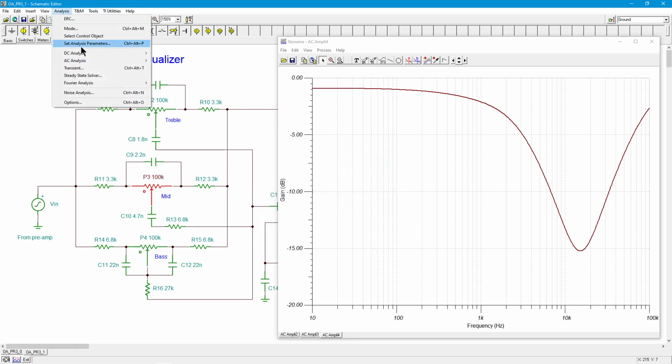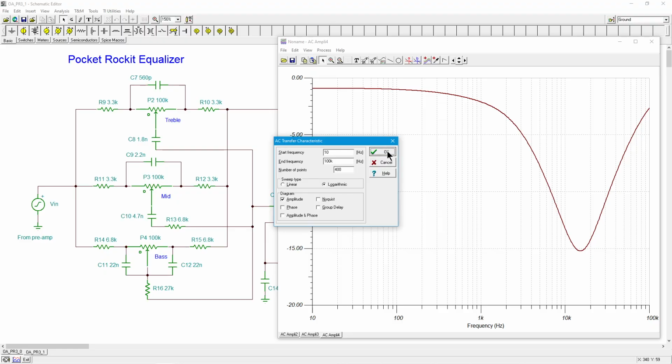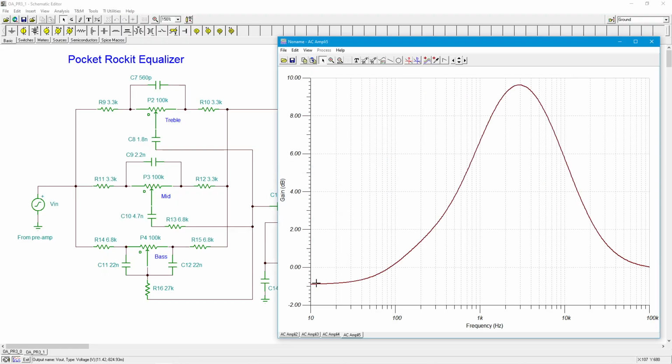So this will be our max. And we can see what the resonant frequency is in the center. All right, so this thing is popping up. We're getting about 10 dB peak, and that's about 3 kilohertz, right? Thereabouts. Here's your 1K, there's 2K, there's 3K. Remember, this is a semi-log graph, right? Logarithmic on the frequency axis. So that's about 3K, and we're getting just about a little shy of 10 dB boost.